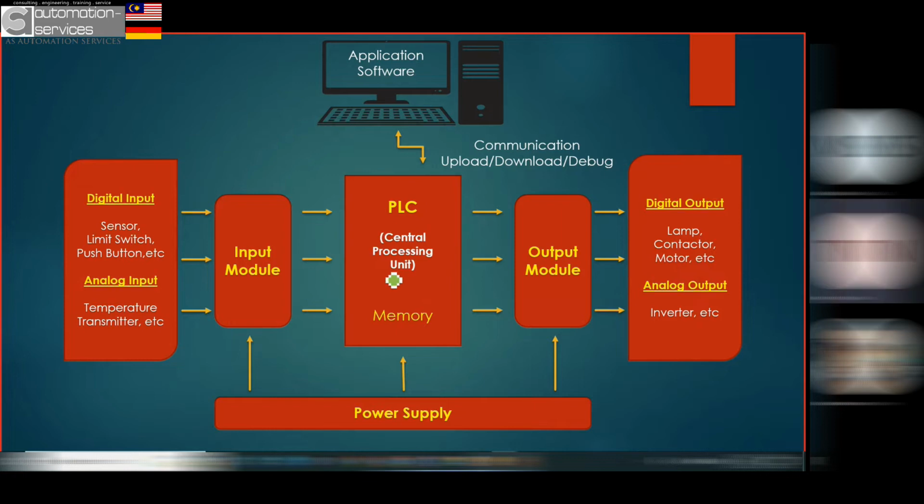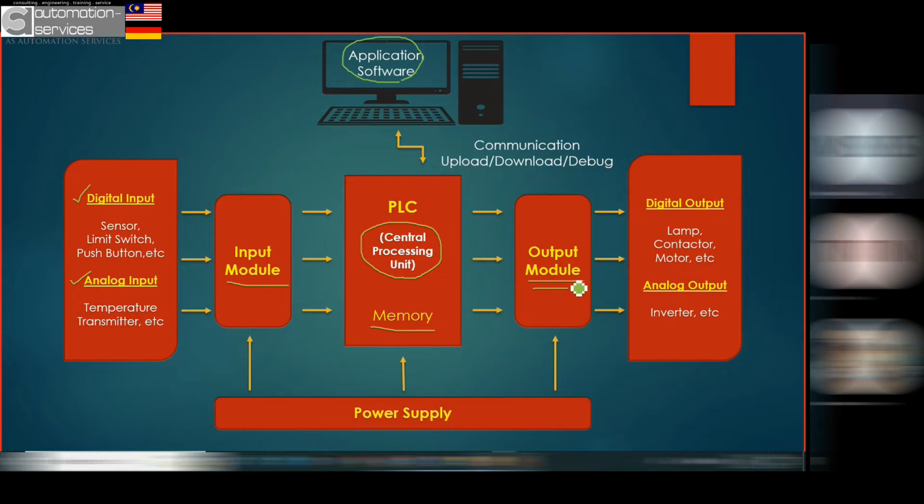They call it a CPU, and the CPU has a memory. Then I connect the input module and output module, and connect all the inputs, like digital inputs, analog inputs, all that. I use the software and download. Then when there are inputs on, it will process in the CPU, then turn on my outputs.